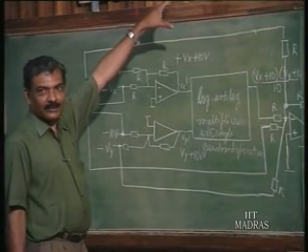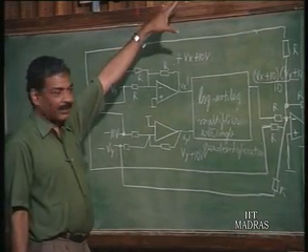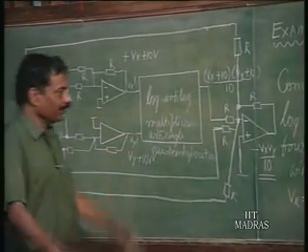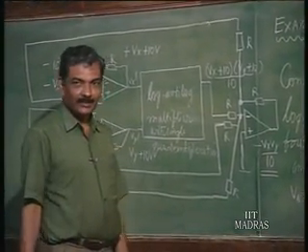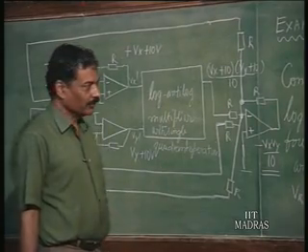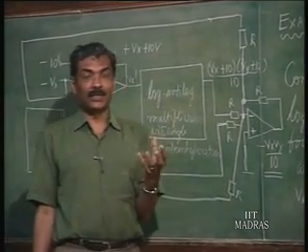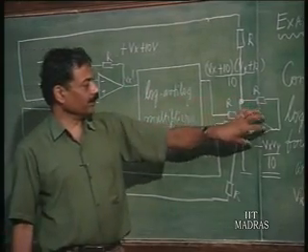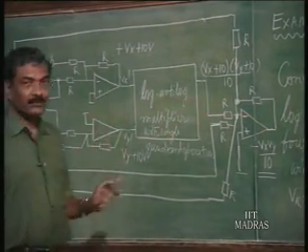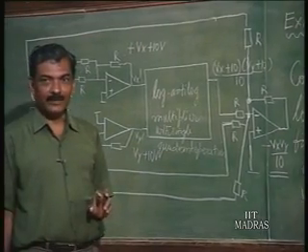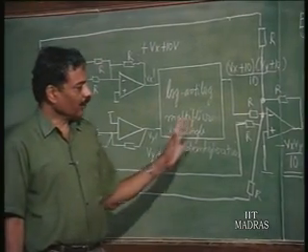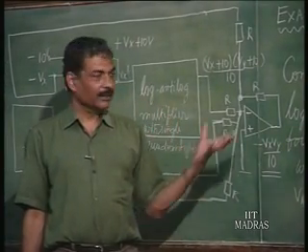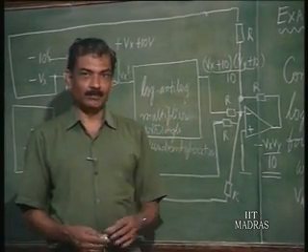conversion using single quadrant multiplier as the basic building block. This is a commonly adopted technique, and the dynamic range remains the same, as what we want, plus minus 10 volts. So, this is a precision multiplier which can be used up to hundreds of kilohertz. Primarily the frequency limitation is due to the op amps, which are not readily available for very high frequencies. So, up to hundreds of kilohertz, if you want to design a very good precision multiplier, this is the technique. This is very cheap.